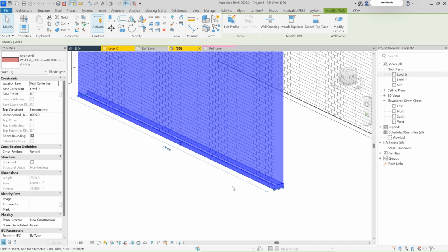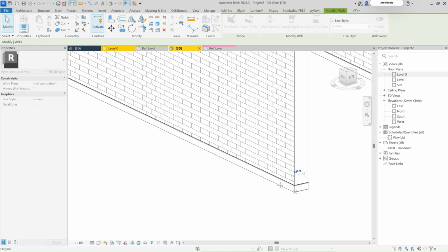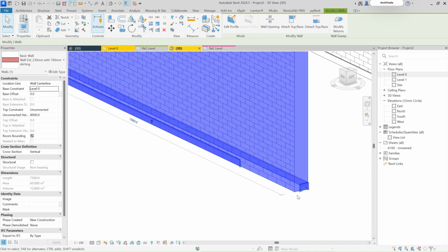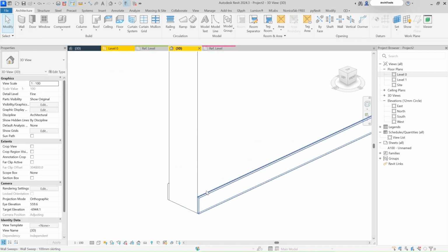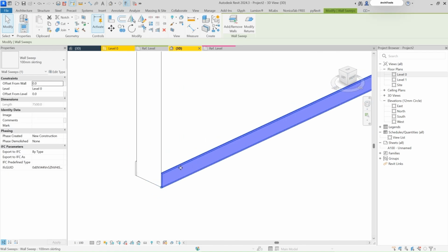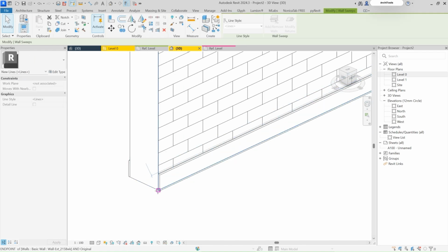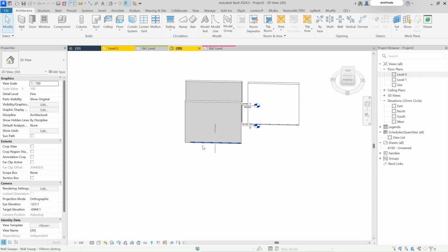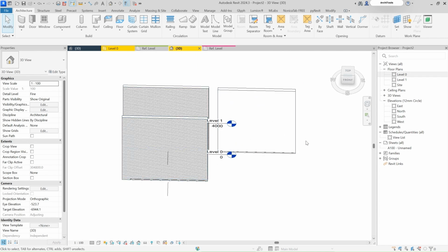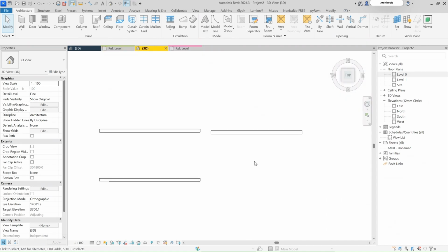And in some cases you want to move your wall sweeps, that is also perfectly fine. You can just adjust the wall sweep using this pointer provided. Same thing applies for the wall sweep option as well. You can just select that wall sweep and move it as per your requirement to place it. So this was basically all of it in order to provide a skirting using the wall sweep and reveal method. I'll just share one more method through which you can provide your skirting, and that is by railing. And I'll leave it up to you which option you want to choose for your provision of your skirting.